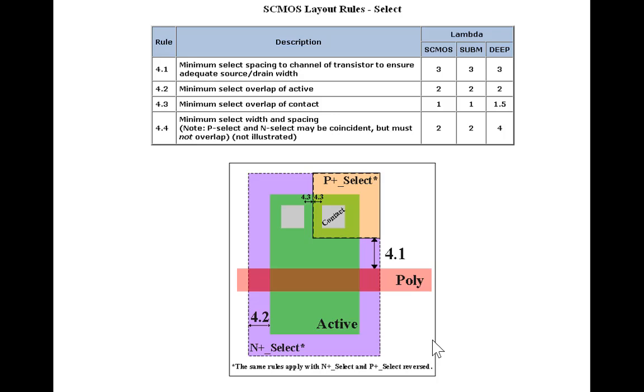You violated the DRC rule, design rule checker. Okay, you have one violation in the DRC errors. It will immediately tell you that. So now in this case, if you draw a polygon, you draw the well, this n-select here, you draw another one, then it will automatically check those spacings. If one spacing is too small, then it will flag, and right there you can move it.